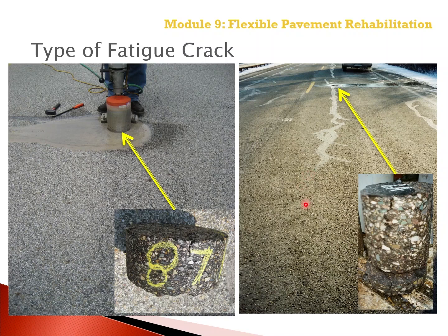The back calculated layer moduli were significantly lower than the undamaged modulus, indicating a lot of damage in the existing asphalt pavement, as compared to the condition on the right, in which the back calculated dynamic modulus values were found to be greater than the laboratory measured or undamaged modulus master curve. And that accounts for the aging of the asphalt.